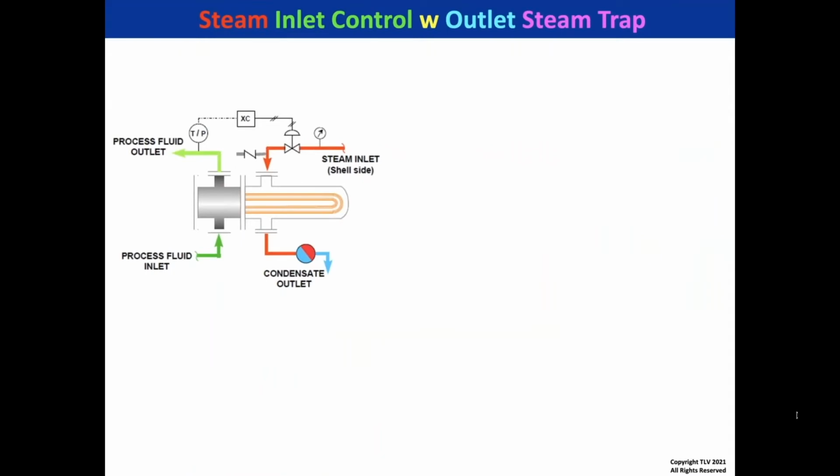So why do people show steam traps? I mean, it could be trap manufacturers. We typically show a very simple heat exchanger like this with a steam trap going to an atmospheric return. Sometimes design engineers do that. That's the basics, right? You start off and say, well, this is a simple way: by putting a trap into the return that's atmospheric, your inlet is always greater than your outlet. So you have a positive pressure differential, super simple.